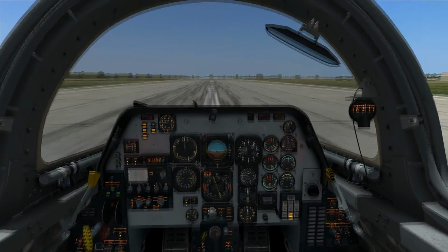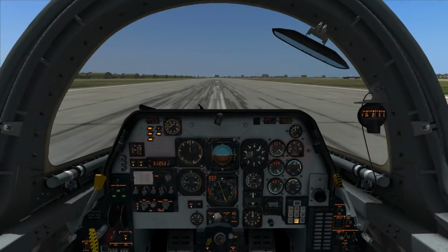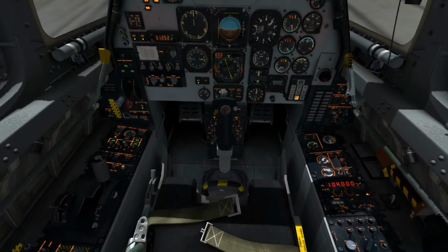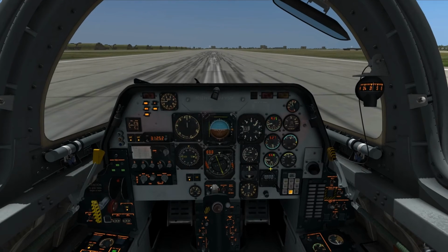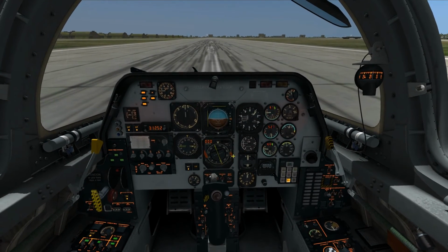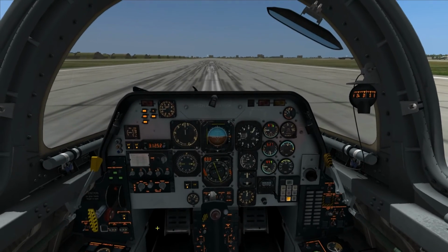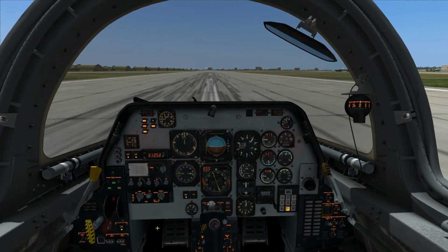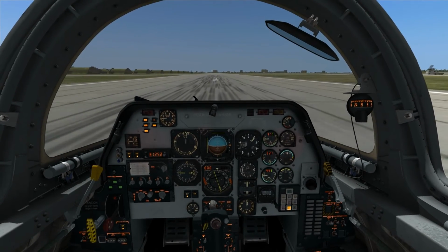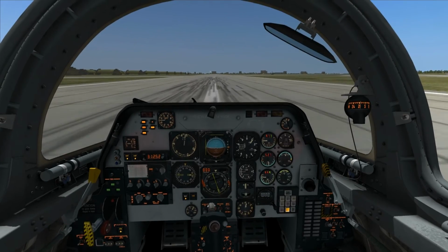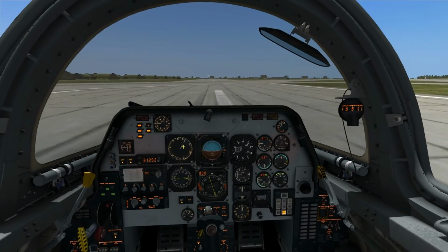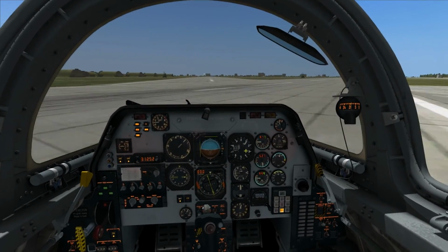On the rear manual of the plane, it says a procedure to take off that is as following. First, we push the brakes, set maximum power slowly, wait for engine parameters to stabilize, and one should be at least 97% stabilizing. Okay, and we release the throttle and 3, 2, 1 now, and start moving. At first, below 40 knots, we can use the differential brake. We check the airspeed indicator is moving, it's alive, all green.